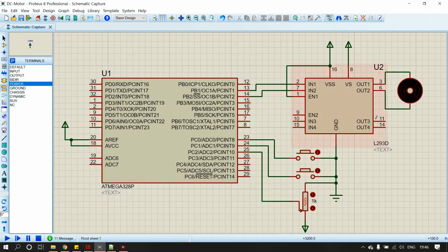So if we see the characteristic of this DC motor and its relation with the driver, if we connect the power input to input 1 and the ground to input 2, it makes the DC motor move in the clockwise direction, and vice versa. And if you see this is a bit laggy, it's because of the hardware of the computer that I'm using.